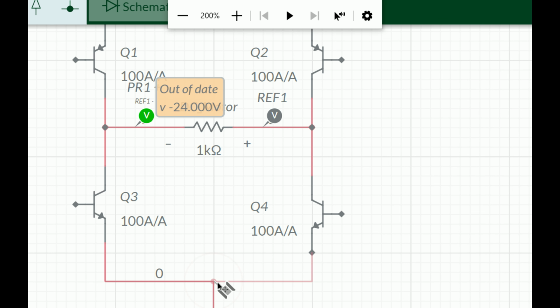Now see the difference. We have replaced the relays with the transistors. Okay, I delete this, it is causing confusion. Now see, this is our new H bridge using transistors. This H bridge has both capabilities. The first H bridge using the switches or relays can only control the direction, while this one will also allow us to control the speed as well.